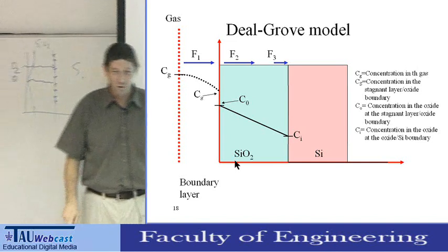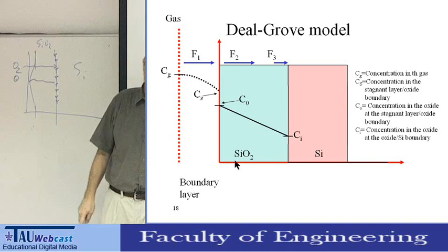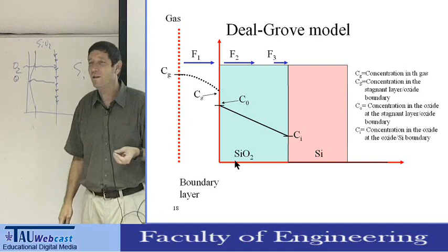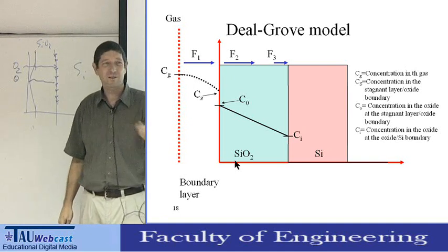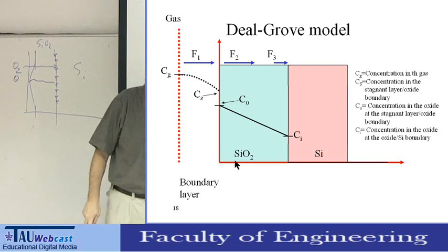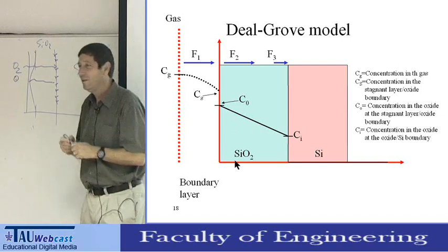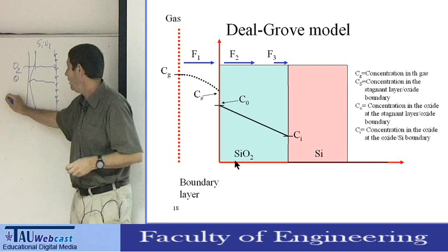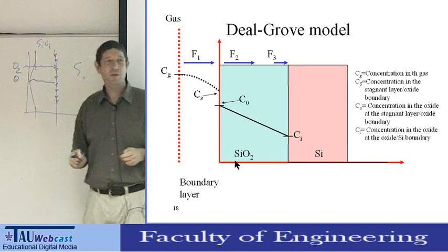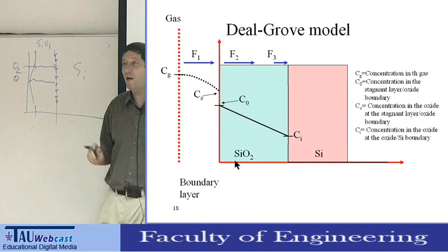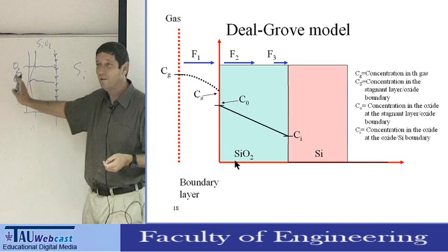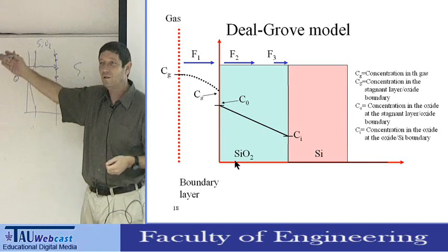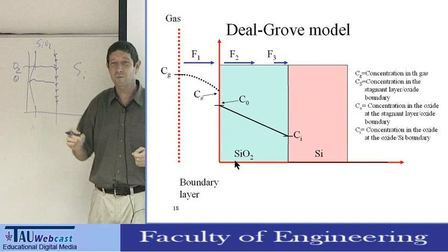First, I can build a model and fit to the model. But let's say I want something more. You have to put in some material scientists here. You have to put some markers. For example, anneal not in regular oxygen but with an isotope of oxygen. So grow some oxide, and then change the ambient to the isotope.